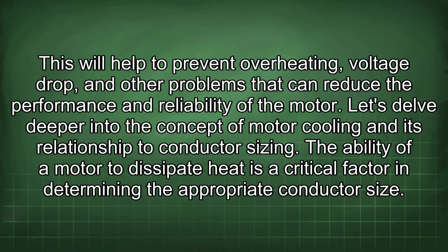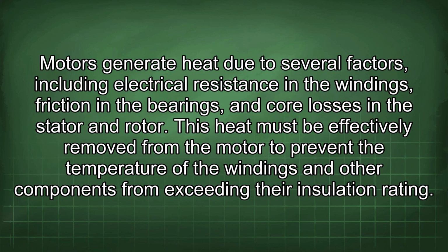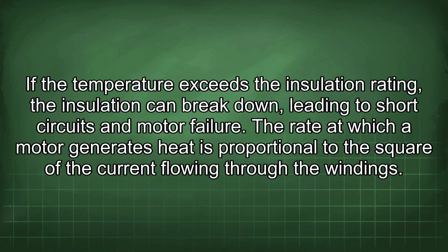Let's delve deeper into the concept of motor cooling and its relationship to conductor sizing. The ability of a motor to dissipate heat is a critical factor in determining the appropriate conductor size. Motors generate heat due to several factors, including electrical resistance in the windings, friction in the bearings, and core losses in the stator and rotor. This heat must be effectively removed from the motor to prevent the temperature of the windings and other components from exceeding their insulation rating.